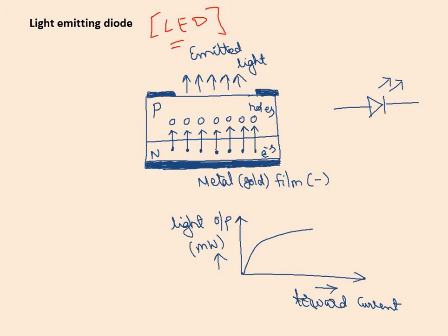You can notice it when you try to press the buttons of the remote and watch that LED through a camera. So open your phone camera and try to place the LED just before the camera lens, so that you can see the LED on the camera screen. The moment you press the buttons, you can see the LED glowing. That indicates that it is working. We can notice whether all the buttons of the remote are working or not by using this. If the LED glows the moment you press the button, it means that particular button is working.